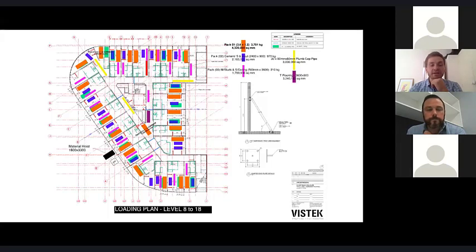But setting that out so that the rooms could actually be fit out at some point, and you could still maneuver around those packs to fix the walls and do all the structural connections and everything. For these types of structures where you do have panelized systems such as CLT that really create those compartments, it's very important to go through this level of detail, I guess, for coordination more than anything.